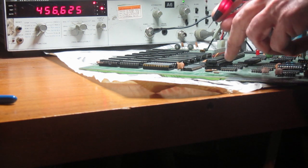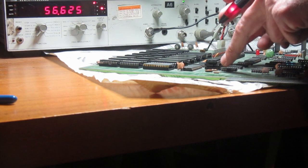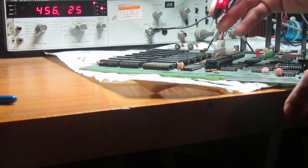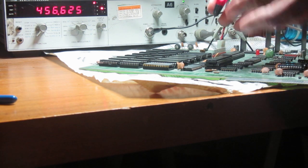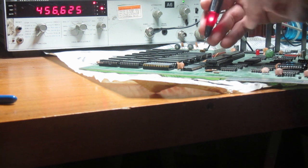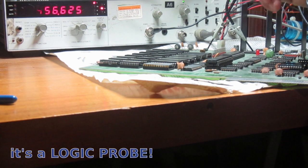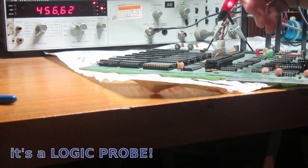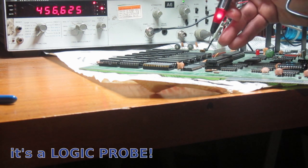So first of all, we inserted the CPU over the NOP generator socket that we have seen in the CPU socket of the board we are troubleshooting. Of course, this 2001 works well, so I don't expect to find any problem, but I'll be showing the use of the logic probe, which is a tool that is not very expensive, that anyone can buy, even new.